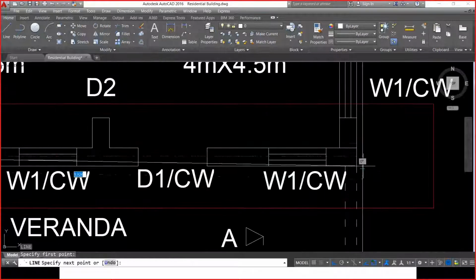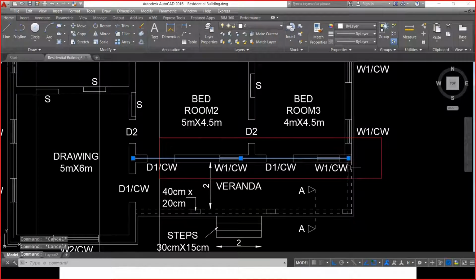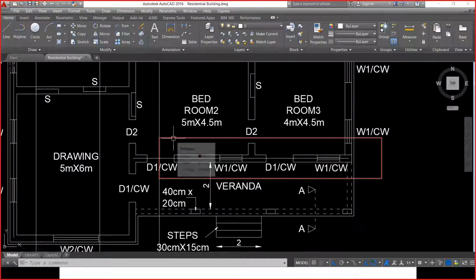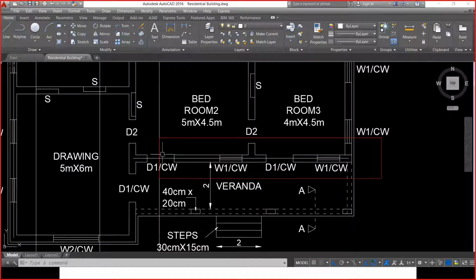It is not always as I have told you in the previous sessions also. If the cases are simple and we do not have any overlaps happening, we can just keep on adding. As a thumb rule, to calculate the length, we can add the width of the item we are dealing with for the length calculation under long walls and do the deduction for short walls. But here, this is a special case where we have junctions and overlap is happening.